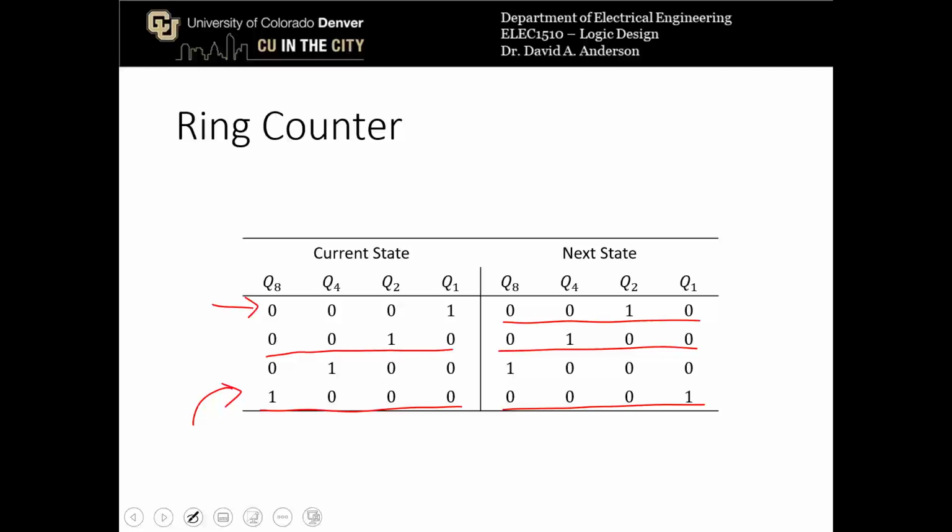You would probably want to introduce circuitry to reset it into this state if you were to get it to behave properly. Otherwise, we could design a ring counter which has an additional state of 0, 0, 0, 0, and then that would also work properly in Quartus.